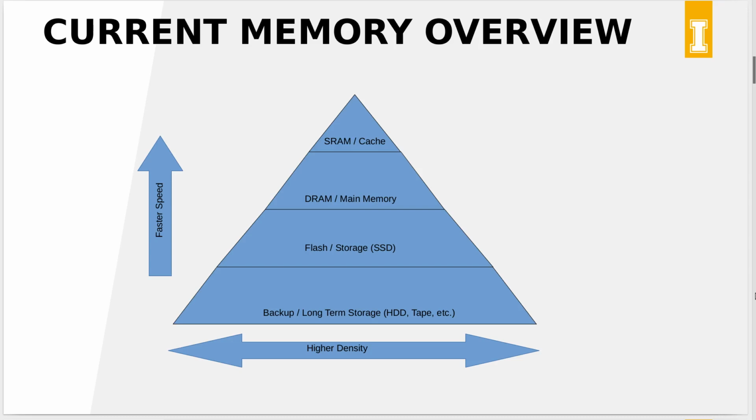regions. To start, you have SRAM, which is a very high speed but very low density memory system that is used in caches throughout. The typical structure for SRAM is 6 transistors and can operate at nanosecond to sub-nanosecond times. DRAM is often used for main memory, is utilized with 1 transistor and 1 capacitor as the storage mechanism for the cell.